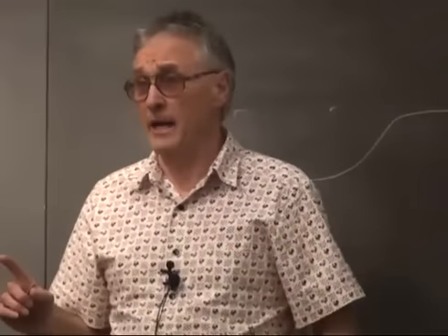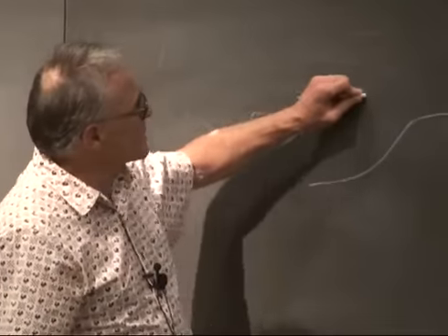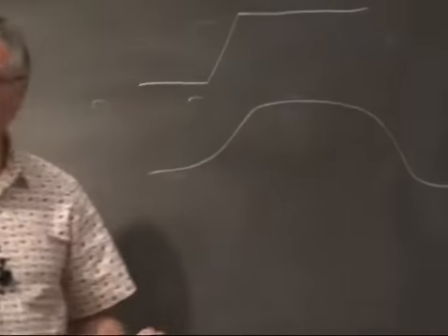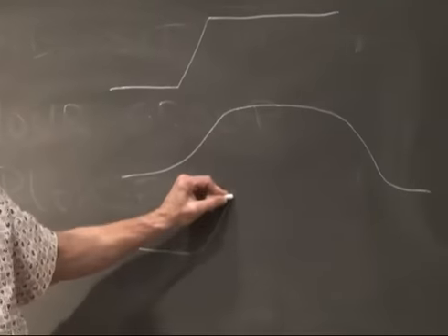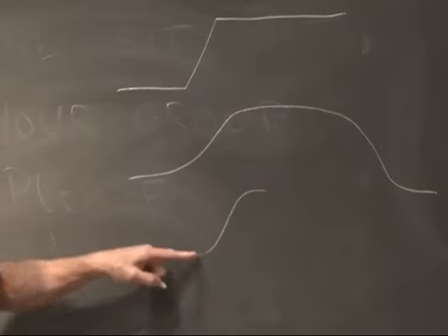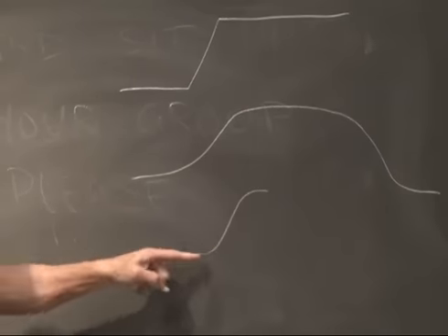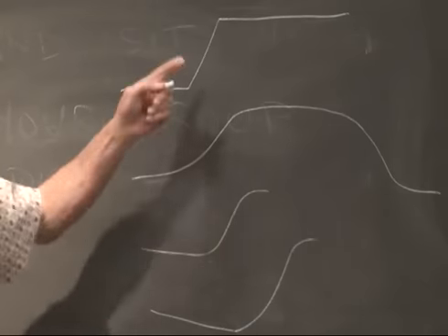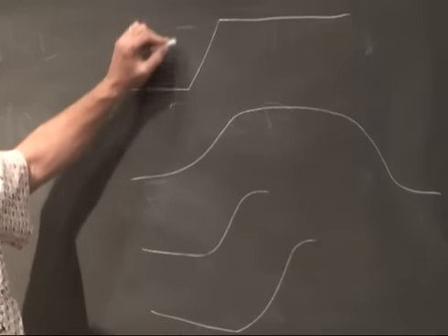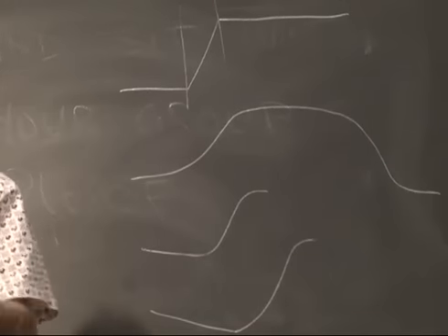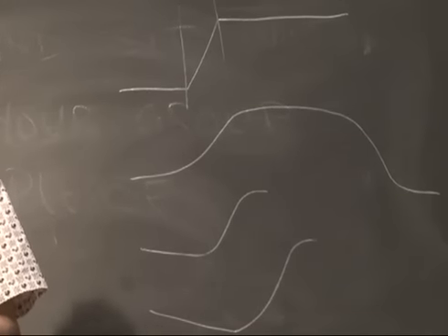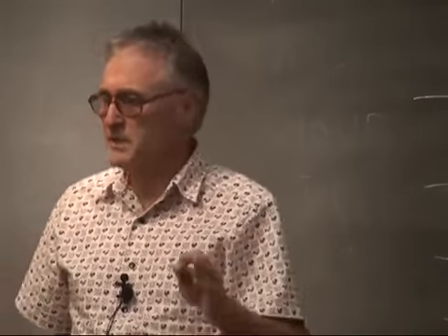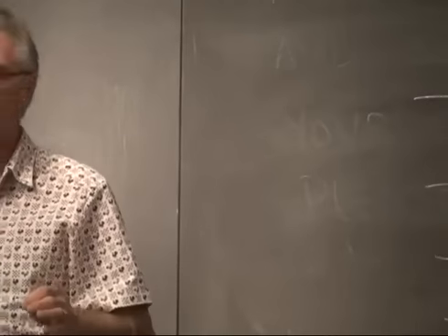I believe that you will find, well, so I suggested one possibility would be a linear ramp. Another is a raised cosine, so it looks like half a cosine wave, and another might be exponential. I think you will find that as long as this transition is long enough, on the order of several cycles, you almost can't tell the difference between those in terms of spectrum. There is a difference, but it doesn't sound very different.